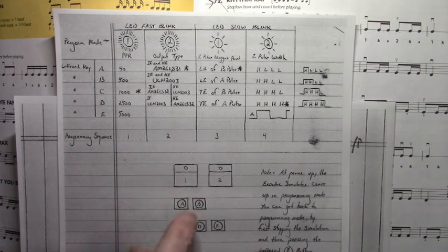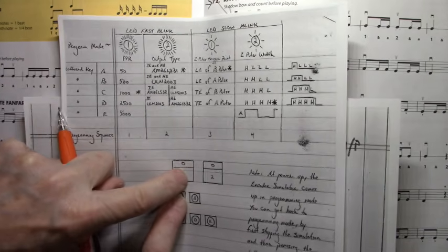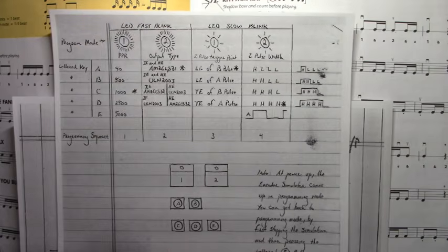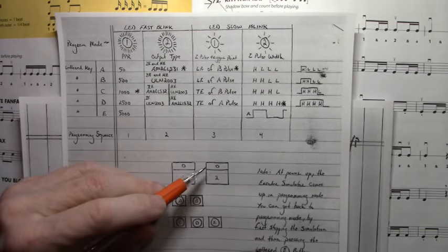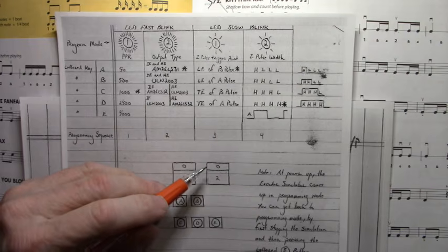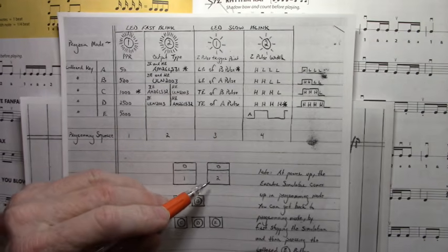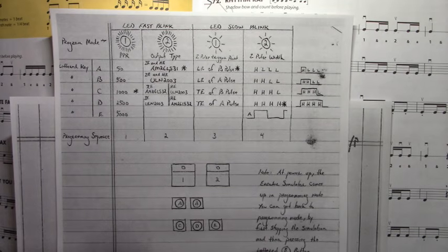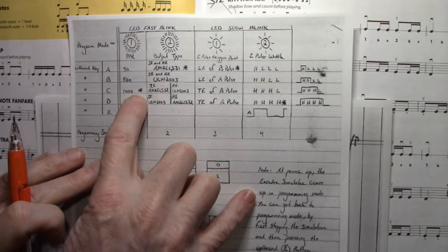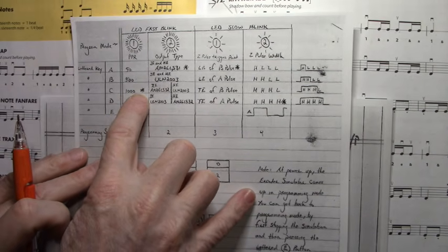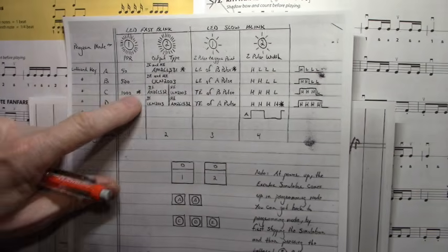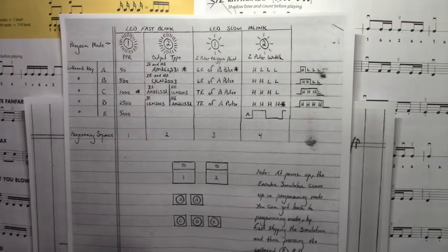So once you push the A switch, you push the number 1 switch, number 2 will start blinking. There's an LED here and an LED here, and the LED on the number 2 switch would be blinking fast. If you want to set the output to the default, which I set to 1000 pulses per revolution, you just push that number 1 switch and the output will default to 1000 pulses per revolution.